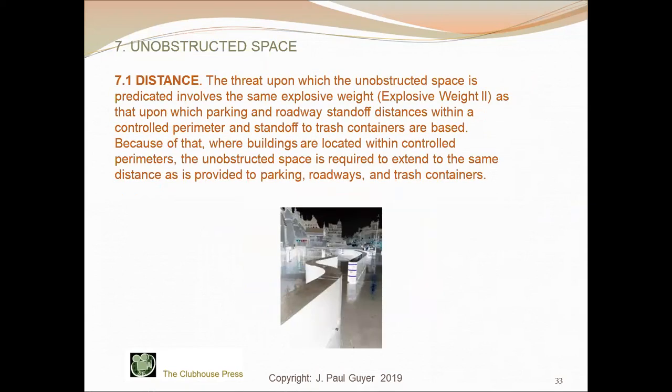Now the threat upon which the unobstructed space is predicated involves the same explosive weight, weight 2, as that upon which parking and roadway standoff distances within a controlled perimeter and standoff to trash containers are based.